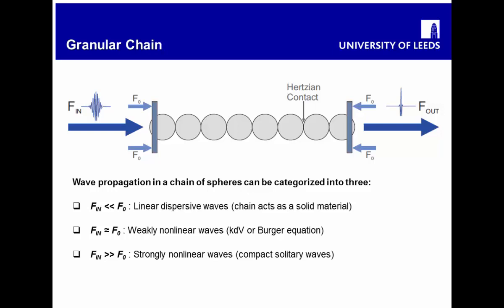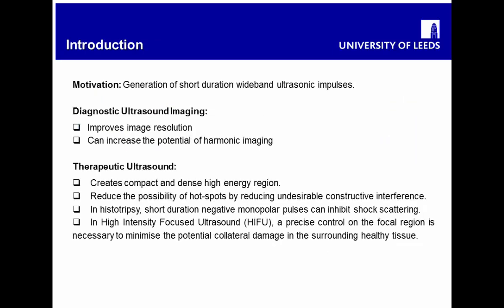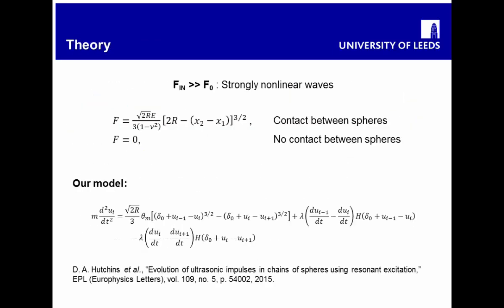And if you further increase the input force, then you will start observing strongly nonlinear effects. When I say strongly nonlinear, I mean the relationship between the force and the displacement is not going to scale linearly anymore, but with a power law of 3/2. So it creates a strongly nonlinear wave. And when the spheres are not in contact with each other, the energy transfer to the next sphere is effectively zero.